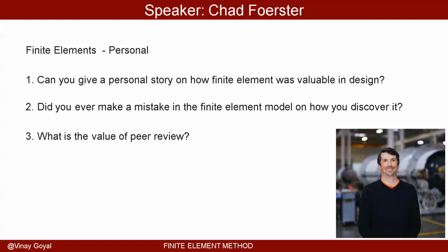It's a numerical method, and it allows you to make decisions, what I said before, it allows you to optimize, and that's really what it is. But it's not the end all be all. It allows you to do these complex systems, so you have to watch your back and help other people watch your back constantly. And I've made mistakes on material properties, figuring in a zero, and then chasing my tail and losing two or three days on an analysis.